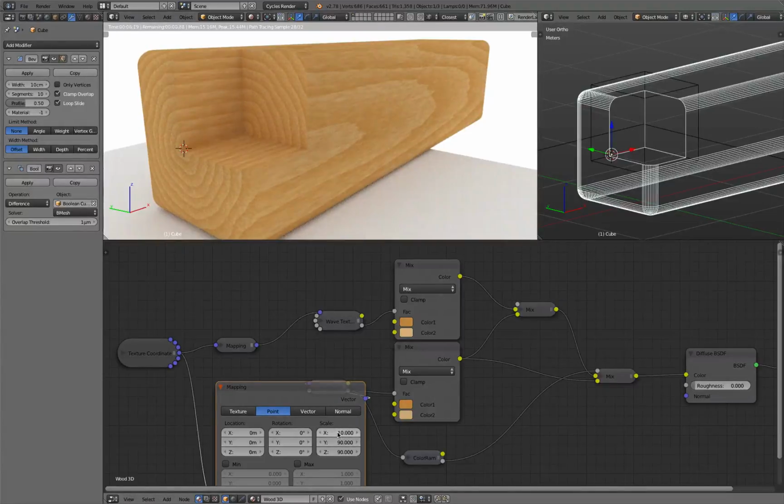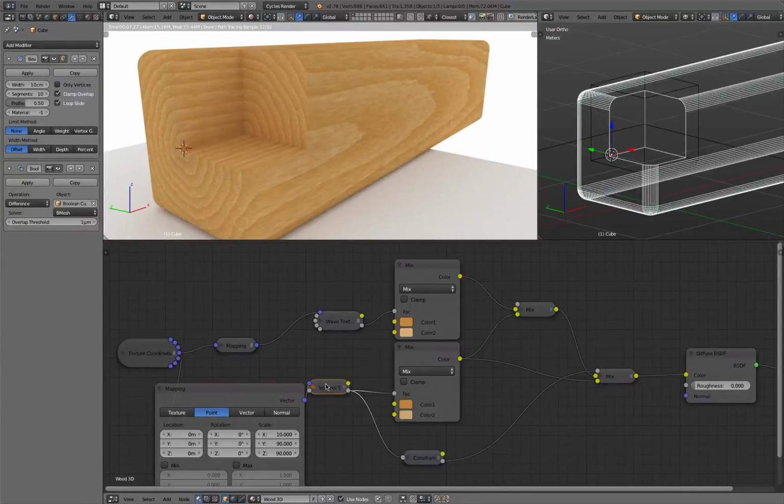So you see, with adjusting this value, I adjusted the look of the texture, which is then being colorized and added to the wave texture. And at the same time, this also adjusts the size for the color ramp texture, which then later we kind of like glue over the whole material as just an emphasis as the pores.